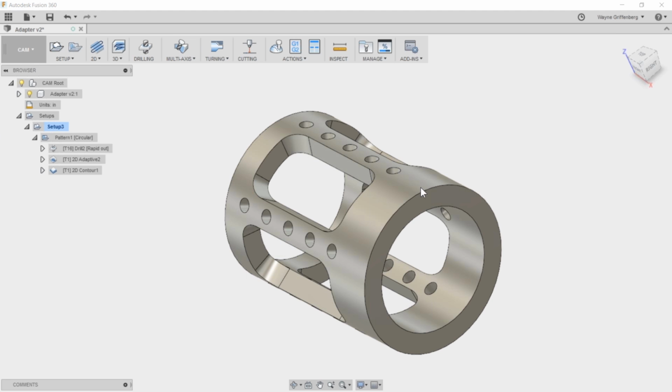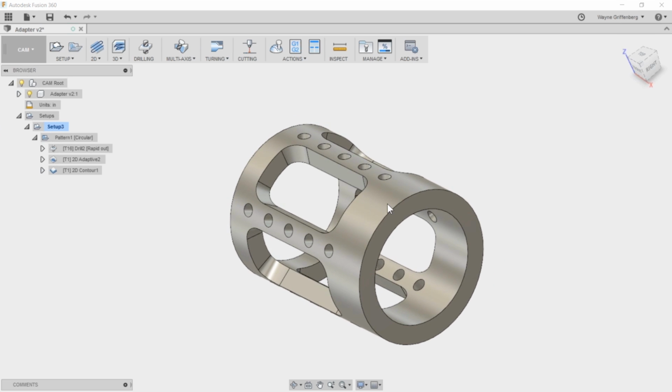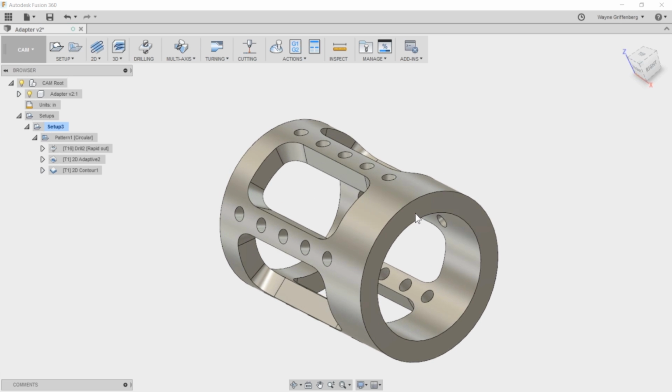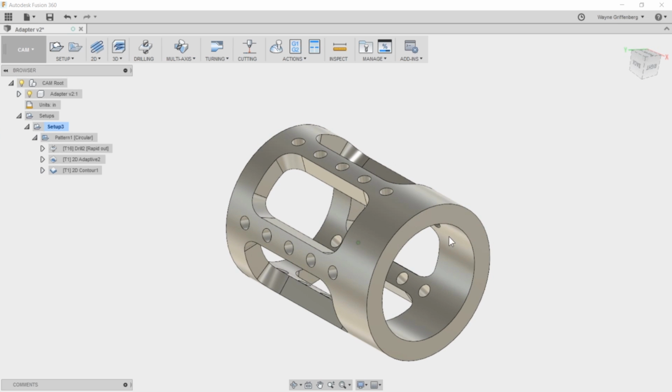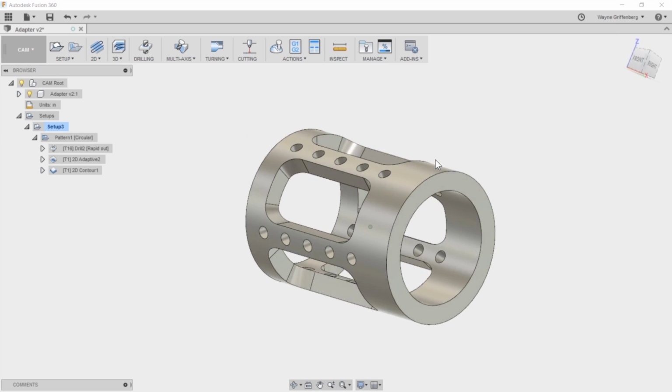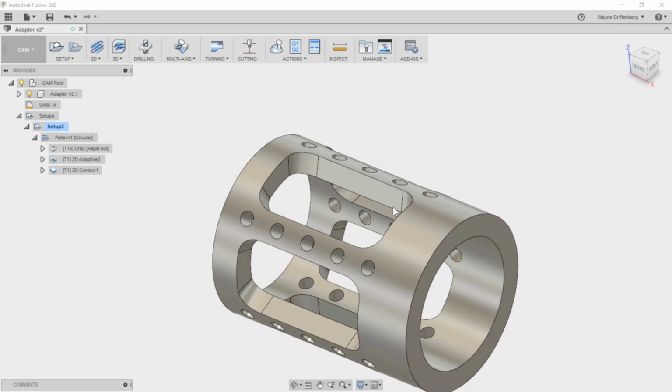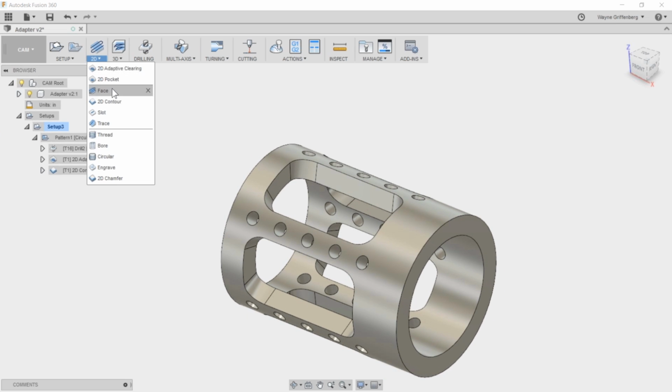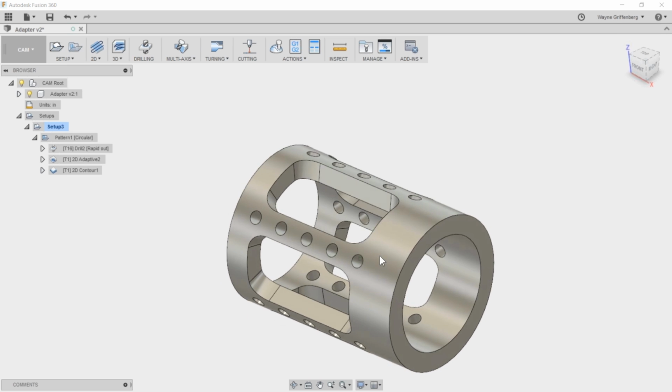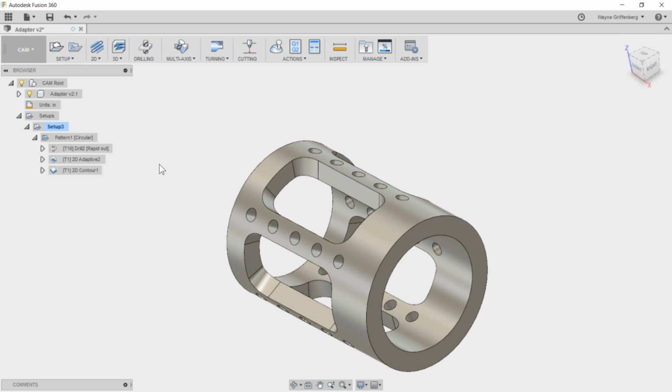Again, it doesn't have to be a cylindrical part. You can always do this on, say, a two-sided part to save your setups. You just do a top side, rotate it 180, and then do the bottom side. So it really saves you a lot of setup if you can do that on your rotary machine. But I really just want to highlight simultaneous fourth axis and being able to do indexing. I don't know if you guys have any questions. I don't really want to go too far past the time, but I hope this has been helpful for you guys.